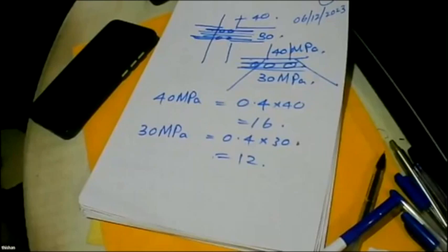But I think that probably the design engineer asked for 40 megapascal, which is not a good thing. And anyway, in Sri Lanka, pile rafts are not necessary. Pile rafts cannot work in Sri Lanka because Sri Lanka has shallow bedrock. Pile rafts work only with friction piles, not with end bearing piles. So it's a wrong concept. Any engineer thinking of doing a pile raft in Sri Lanka has to be very careful.